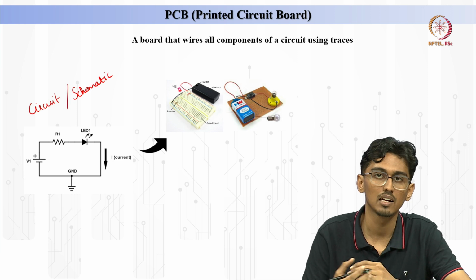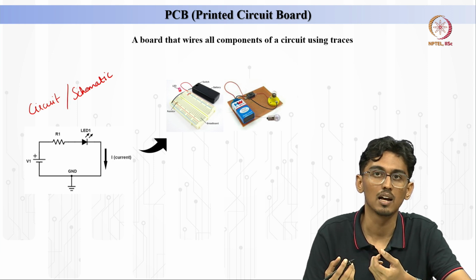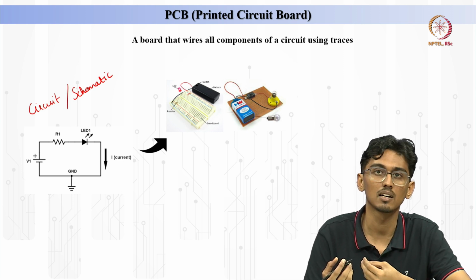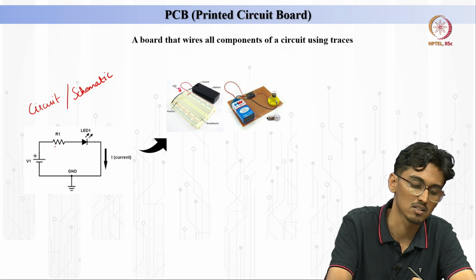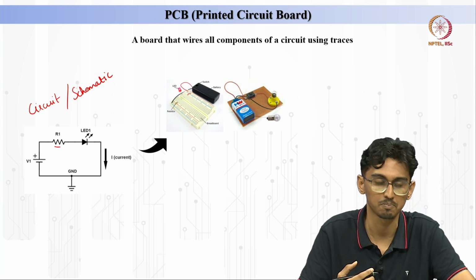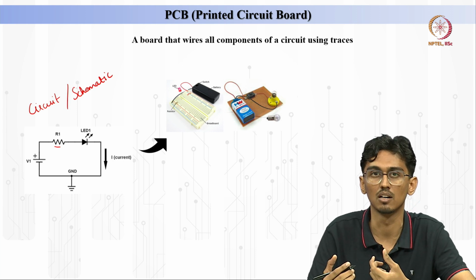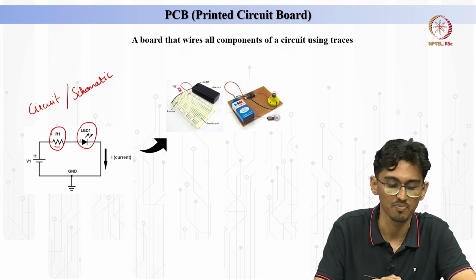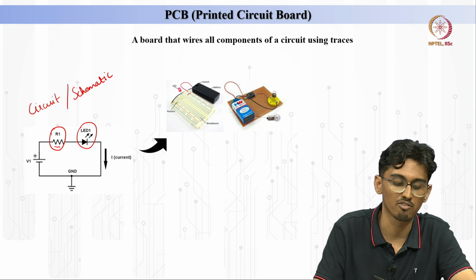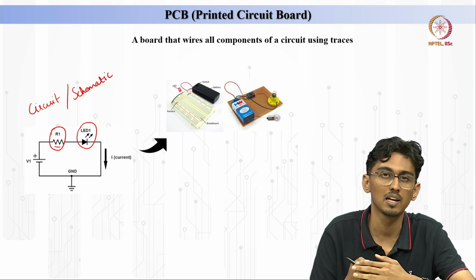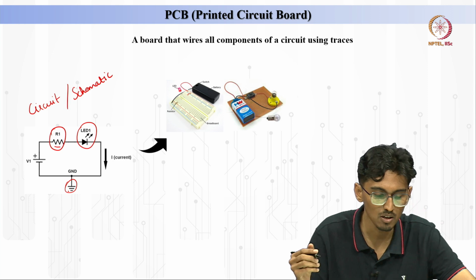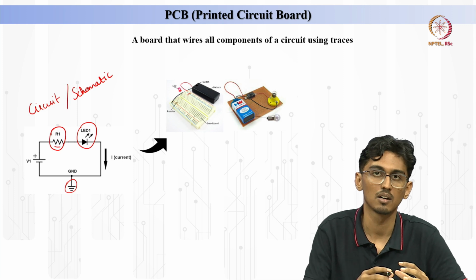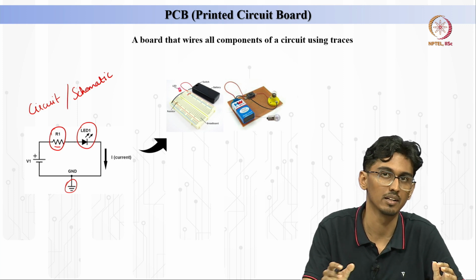As we all know, any light emitting source can heat up, and whenever any element heats up in an electronic circuit, the current goes out of control. In order to limit the current, we have to have some form of limiting factor, hence a resistor. In this case a resistor is used, and then we know that a fixed current will flow across the circuit, because R1 and LED1 are in series. And of course we need a reference plane for us. In our case it will be the ground. Now no need to worry about the schematic, but I just wanted you to understand this circuit so that you can appreciate the rest of the circuits.